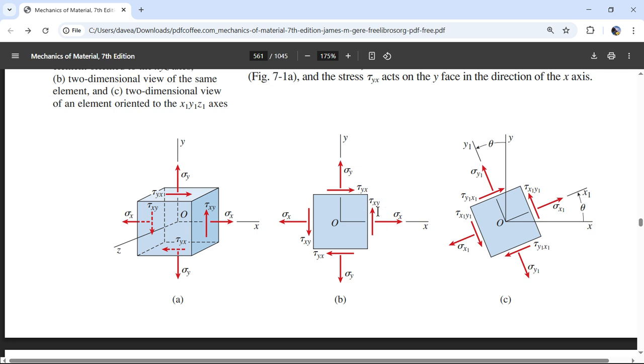This is where it's useful to have this. If I just had a free body diagram and I said there was a force acting up on this, and then I just went to cut this cube right here, well, now look at this. I'm not going to have that total force acting on this new cut surface, but I am going to have the same pressure. And so when I cut this at a 20-degree angle, and it still has thickness into the board, because we still have to talk about areas, right?